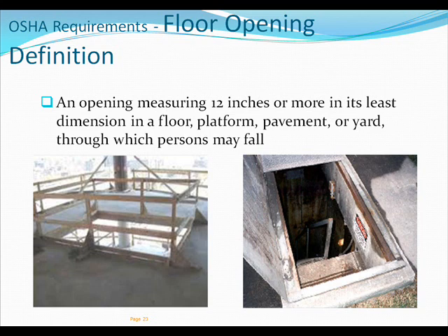Floor openings. An opening measuring 12 inches or more in any floor, platform, pavement, or yard through which persons may fall, such as a hatchway, stair or ladder opening, pit, or large manhole. Floor openings occupied by elevators, dumbwaiters, conveyors, machinery, or containers are excluded from this subpart. Note, every skylight must be guarded by a standard skylight screen or fixed standard railing on all exposed sides.